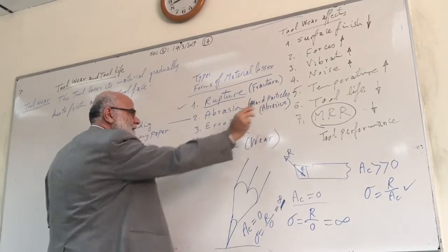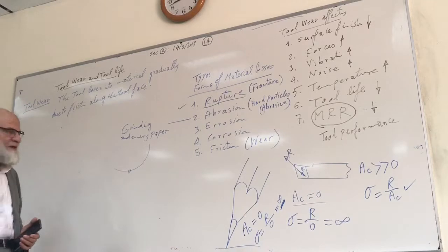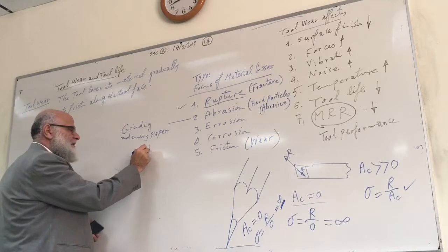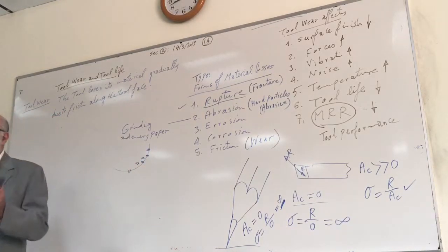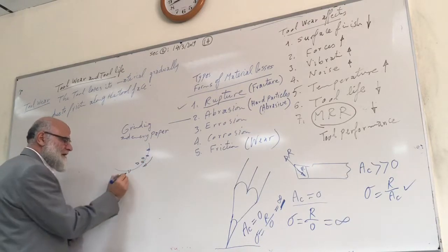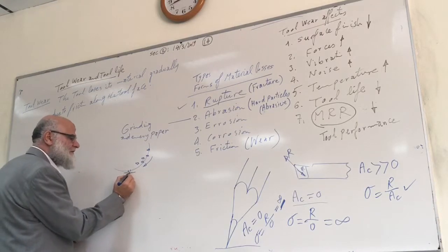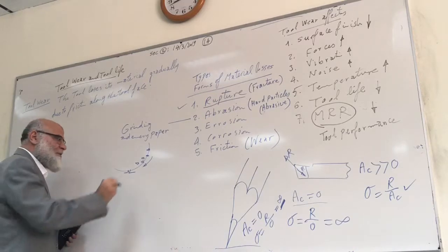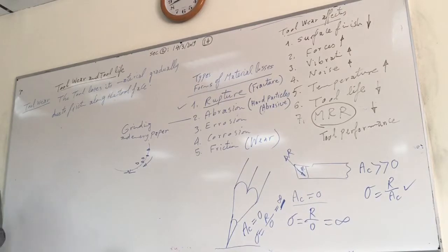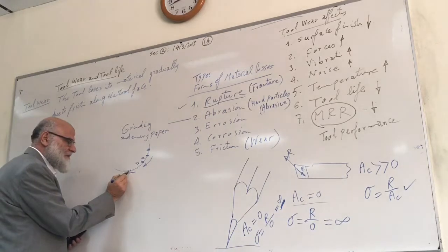This is the grinding wheel. One of the hard particles here is like this, going out with a sharp edge, and the grinding wheel has many particles like this, bound with material, forming a wheel. When rotating at high speed, it will cut a chip, a very small chip. This is the unmachined surface, this is the machined surface of one particle. How many particles are there? Hundreds. Revolving at high speed, millions of times this particle will be removed.